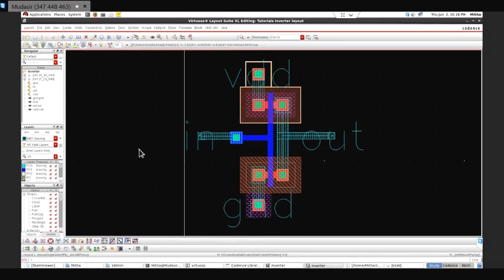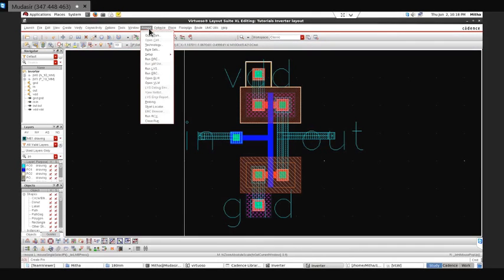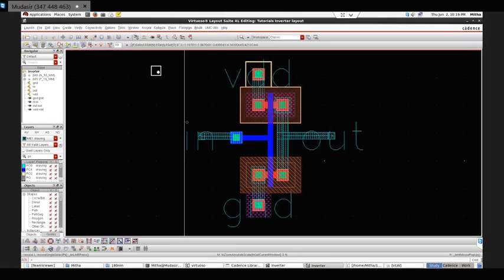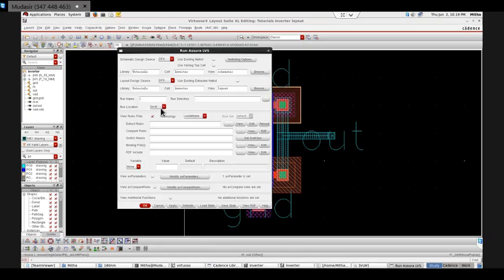So once DRC is done, everything's connections are right. So next thing is to go for LVS. We are comparing our layout versus schematic, whether everything is matching or not. If something is matching, something is not matching, it will be shown. Okay. So these are relative tools. They are generally cleared by DRC and LVS, so not required to do this ERC.